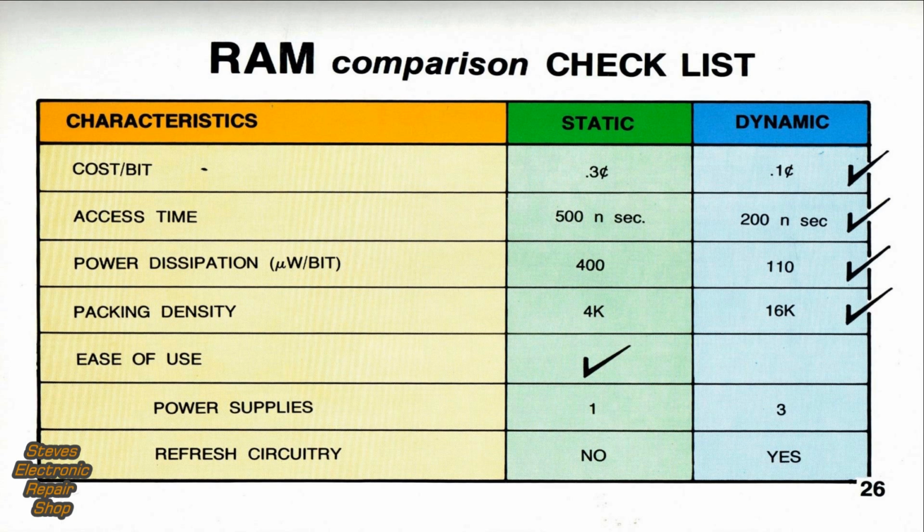case. However, one other consideration that's extremely important is ease of use. Here the static RAM wins hands down, since it only requires one power supply and doesn't need external refresh circuitry. In some cases, ease of use is the determining factor for selection.